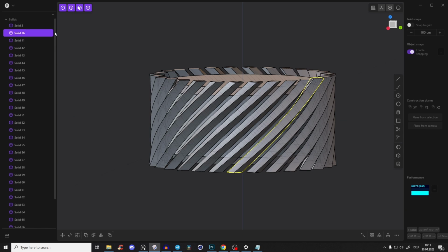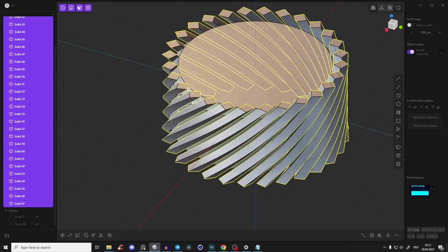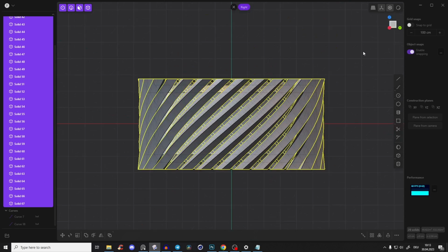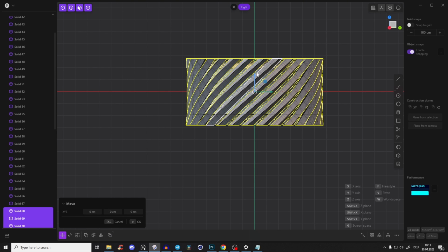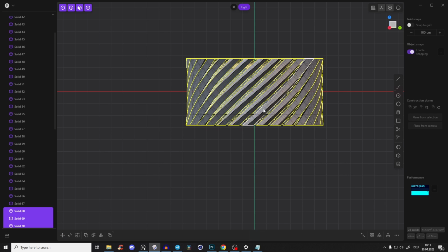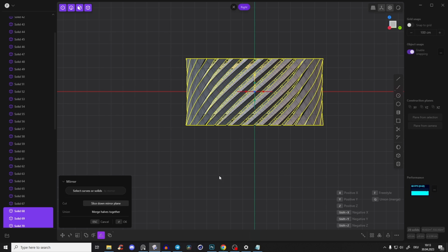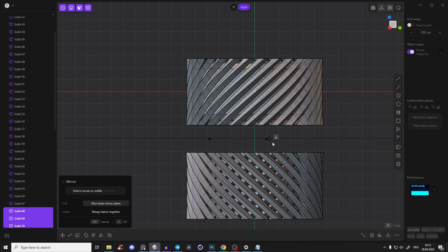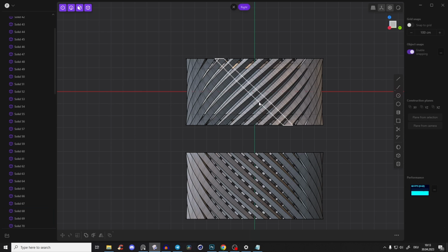And now, they were all selected, but I will just select all of those outer bodies, press Shift D to duplicate it. So we have 2 of them, but now we have to mirror them. So I press Alt X and I press just F, so I can create the line where I want to mirror it. And I will just click any point, and drag a straight line. So you see one is going in one direction and the other body is going in the other direction.